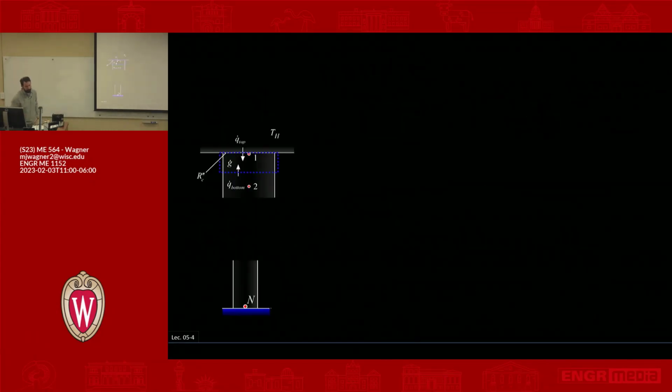So let's repeat this for the n nodes, starting with node 1 at the top. Node 1, again, is right on the boundary. We don't know the temperature of node 1, but we do know that there's a contact resistance, and we know something about the hot side temperature that on the other side of the resistance it's exposed to. So we're going to need to account for that.